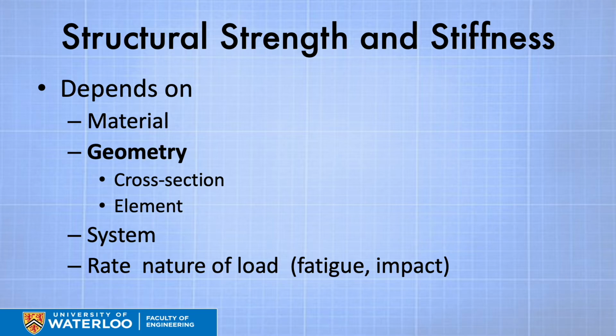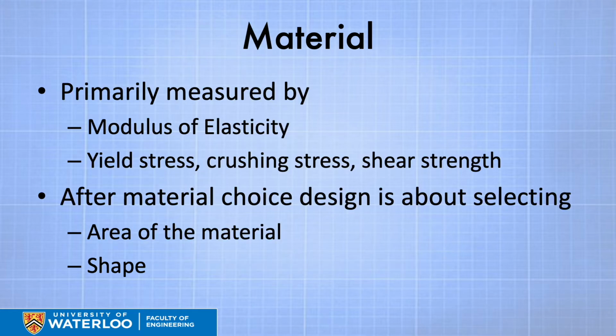So materials such as wood, bamboo, and other natural materials tend to be much stronger under short-term impact loads than under long-term, year-long, century-long loads. Materials like steel generally are pretty similar over longer time periods, although they may be a bit stronger when it comes to short-term loads. And other materials actually are more sensitive to impact loads than they are to long-term loads, materials like glass.